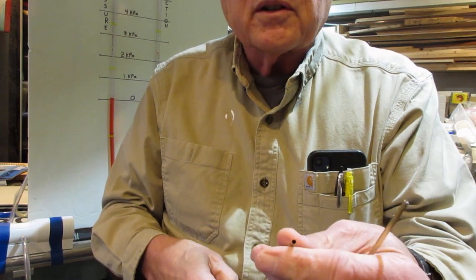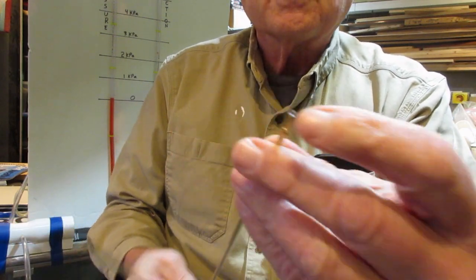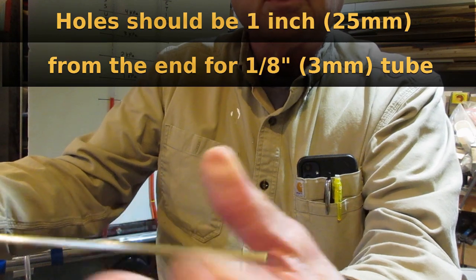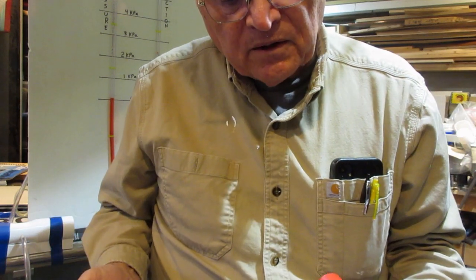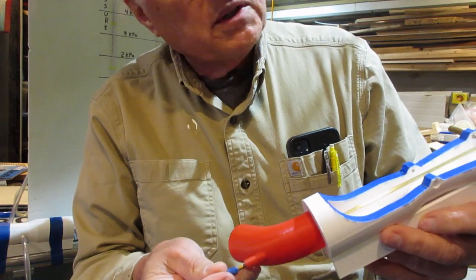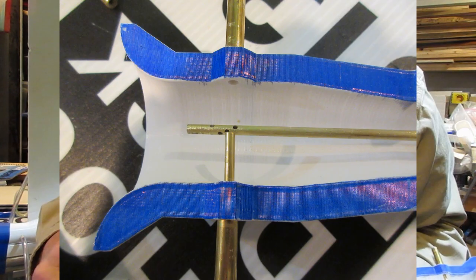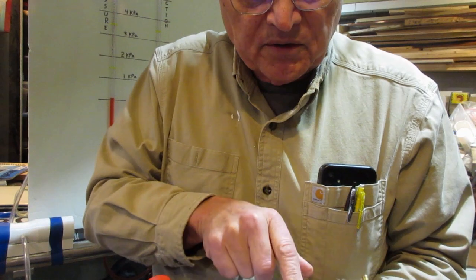The other option would be to make some static and dynamic probes. The total pressure or Pitot tube is just open on the end, and then this one has a little dab of epoxy in the end and some holes drilled in it to measure the static pressure, just the ambient pressure. And I have these marked when I slide them in. So that mark is the beginning of the Venturi. That mark is where the holes are about lined up right here. I got another mark there. And you could get the same measurements lining those marks up that you get with these probes.